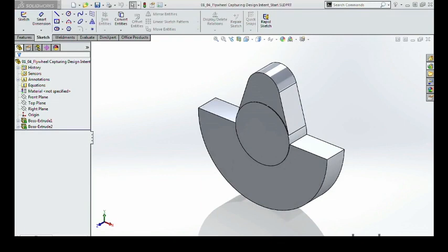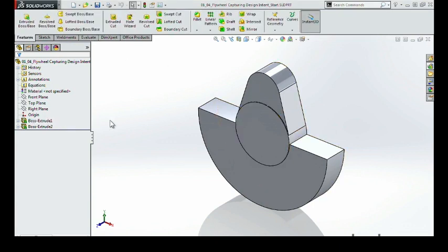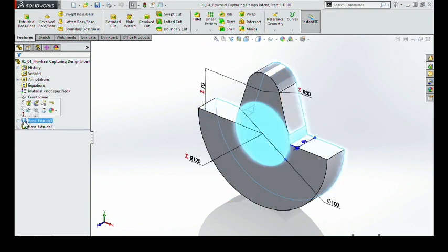In the first video of this chapter, we used equations to capture the design intent of the sketch. We can visualize this using the Instant 3D capabilities of SolidWorks. The Instant 3D toggle command can be found on the Features command bar. Click on the first feature in either the Feature Manager or directly in the Graphics view. This will show the selected feature's dimensions. Blue dimensions are measurements entered into the feature's properties, in this case, our extruded depth. Black dimensions are what we have created at sketch level. Notice the little blue orb on the circle's dimension.